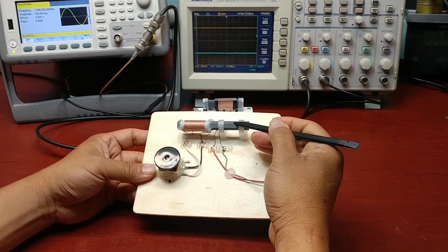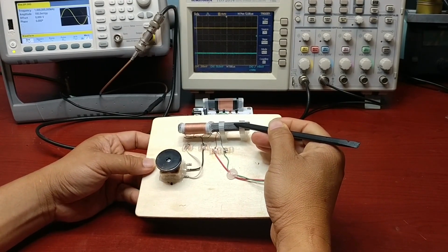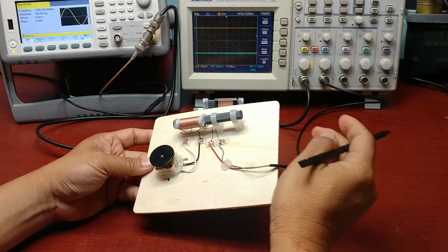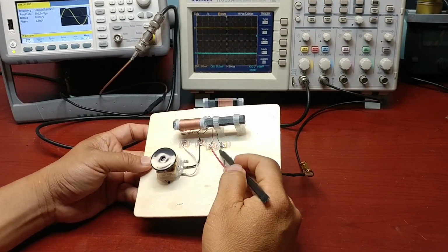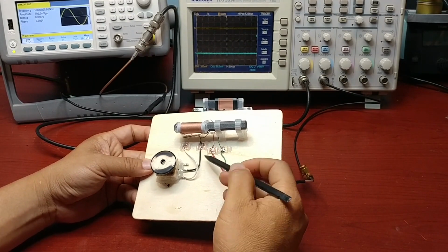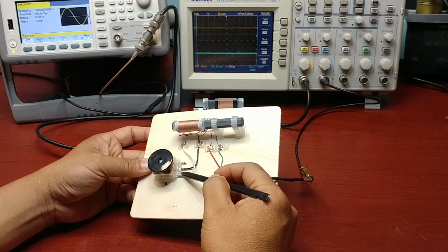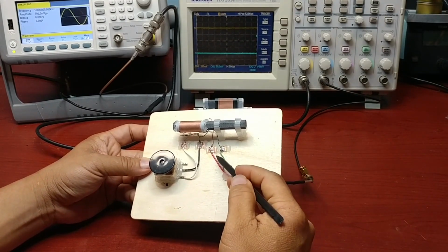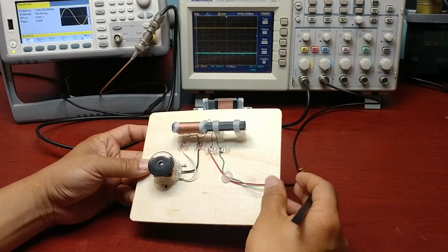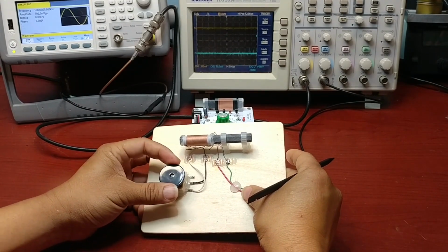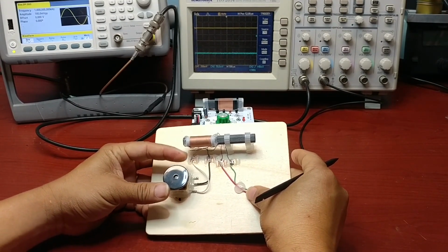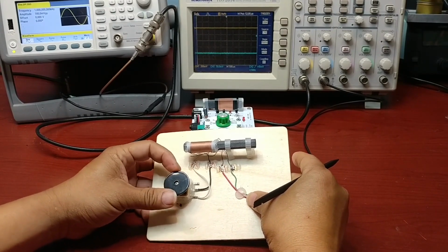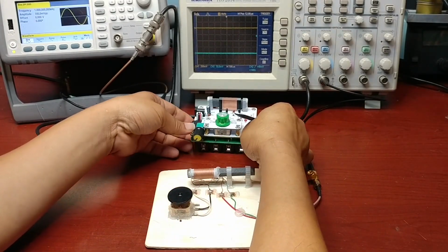Here is an AM radio receiver antenna circuit. The antenna includes two coils, a big coil and a small coil. The big coil is connected in parallel with a variable capacitor, forming an LC-tuned circuit. The small coil is the antenna signal output, and is connected to the scope channel 2. When the receiver antenna circuit is in tune with the transmitter frequency, the antenna catches the radio signal from the transmitter.